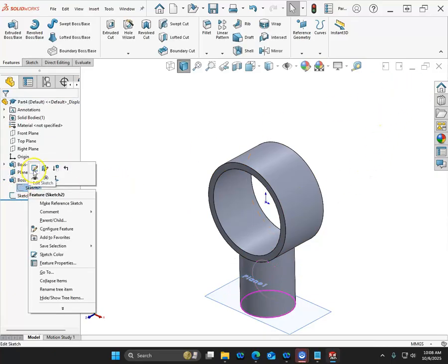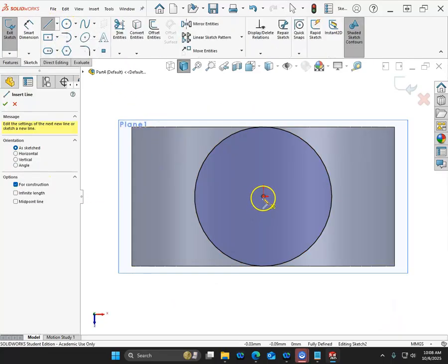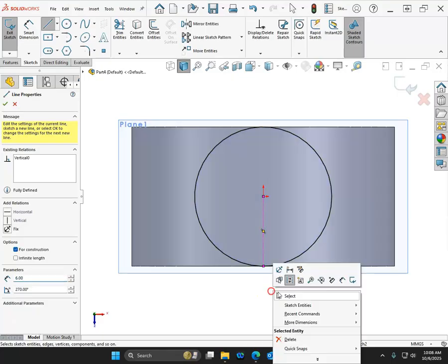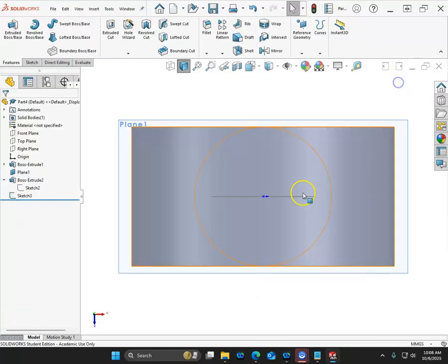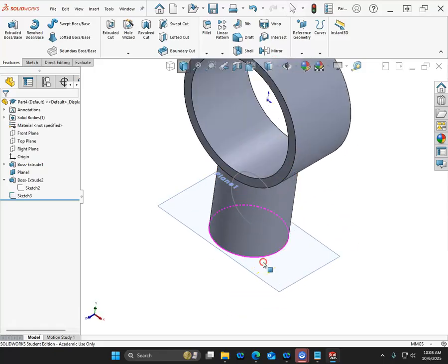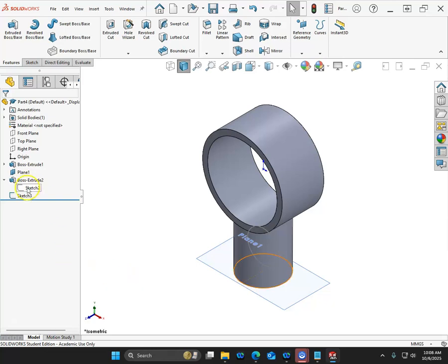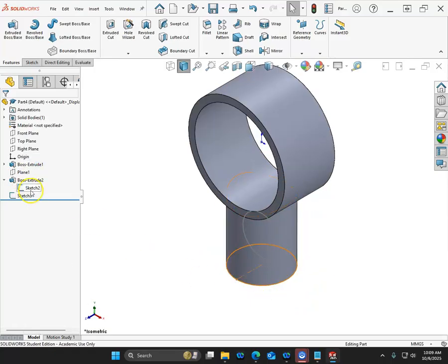And because we have that circle, I can always drop in a center line that represents where that geometry ends up. All right, so I'm just going to hit Control 7 because I'm having too much fun with the middle mouse button. We're going to show Sketch 2 because now it has that geometry, and I can hide plane 1.